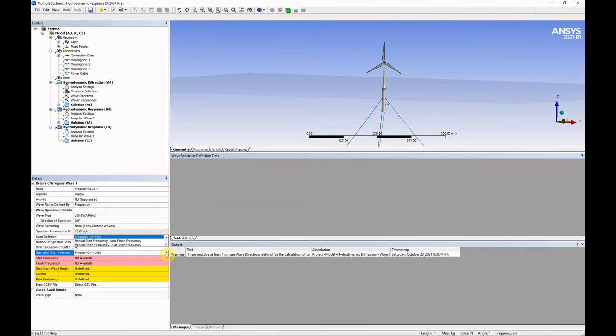Let's control manually all the wave parameters. Let's also change wave range definition from frequency to period. To model some kind of storm wave, let's use a wave spectra with a peak period of 16 seconds, as an example. The gamma factor, start and finish periods are needed.